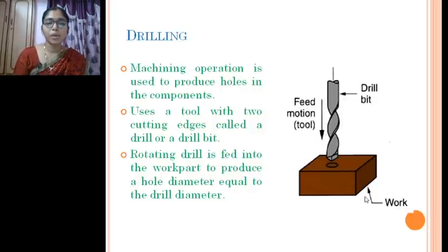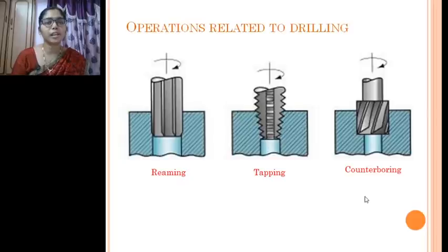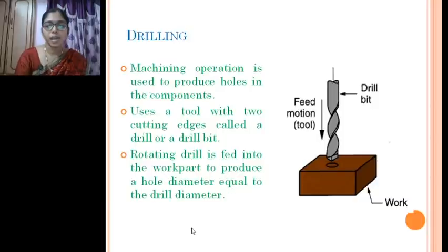As you can see, for example, a drill bit is used for making or producing holes. Now how does that work? It has two cutting edges which remove the material. Due to the rotary motion of the tool, the cutting edges penetrate into the workpiece, thereby stresses develop at that particular point, and the material is lost from the surface. Like here you can see a video.